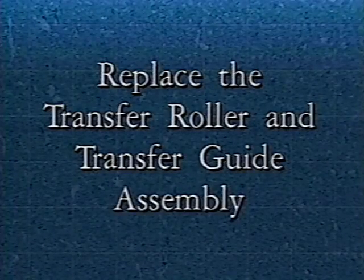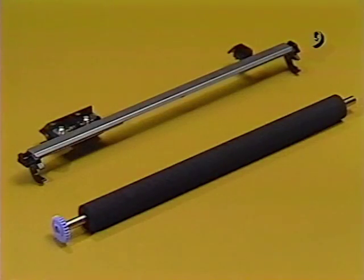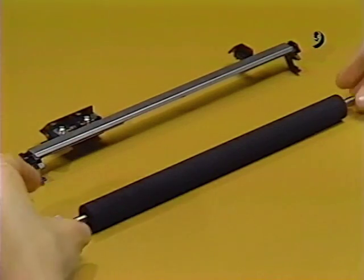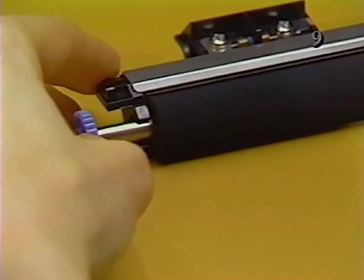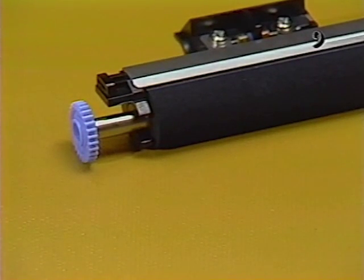Replace the transfer roller and transfer guide assembly. Begin by placing the transfer roller inside the black plastic arms on each end of the transfer guide assembly. Then snap the transfer roller into place. Make sure the blue gear is positioned on the same side of the transfer guide assembly as the silver grounding plate.